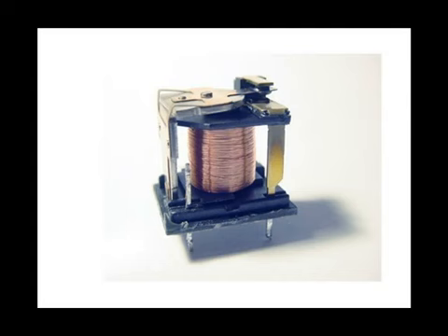The normally closed contact is used to determine if the relay is de-energized, and the normally open set of contacts are used to determine if the relay is energized, or you could say that the normally open set of contacts are used to determine if the set of conditions that energize the relay is a true statement, whereas the normally closed contacts are used to determine that the collective conditions are not met or false.